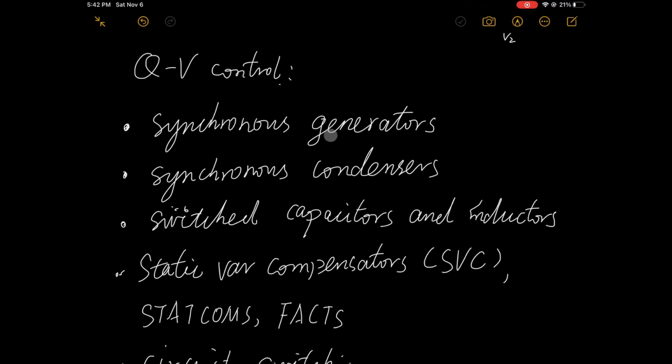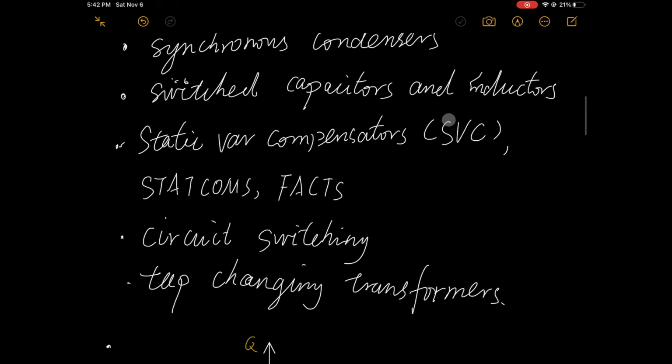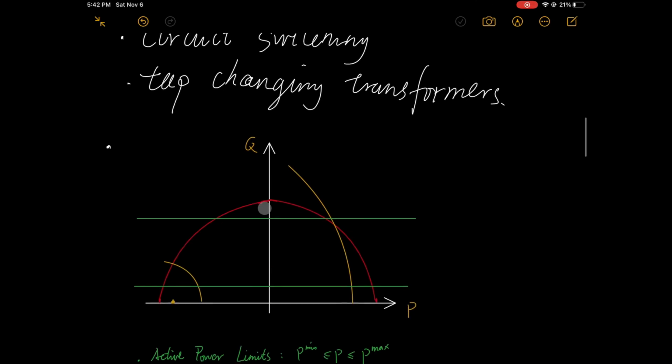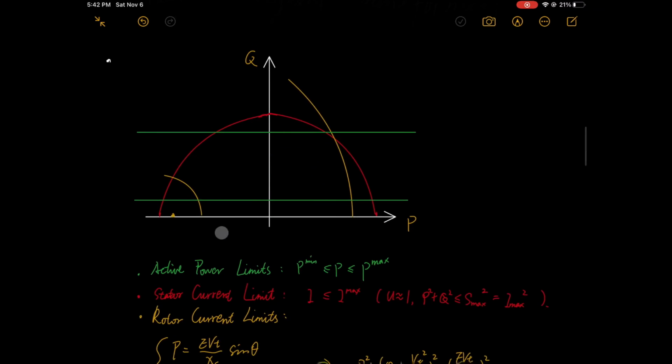First, synchronous machine. The basic idea for synchronous machines is that changing mechanical torque can adjust power angle, and changing field current can change excitation voltage amplitude. They can be controlled separately. Now let's talk about the limitations on synchronous generator operation.